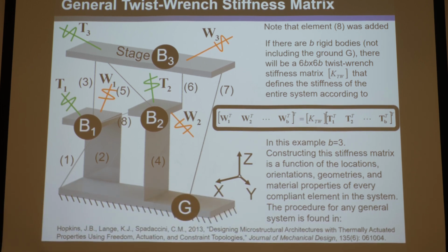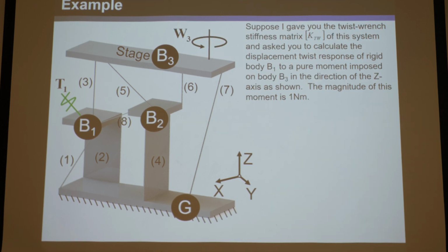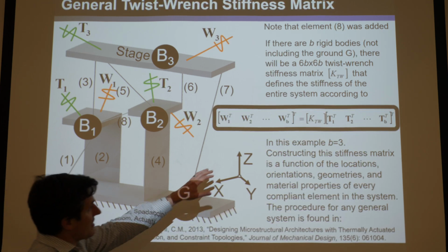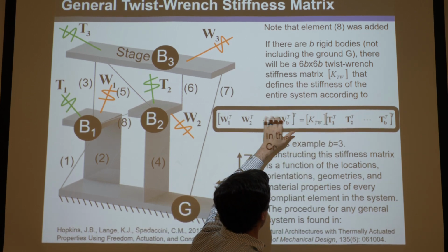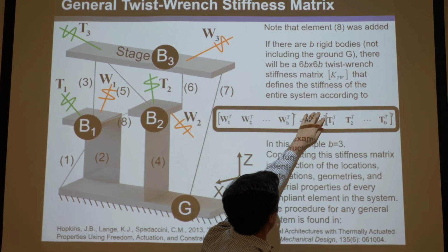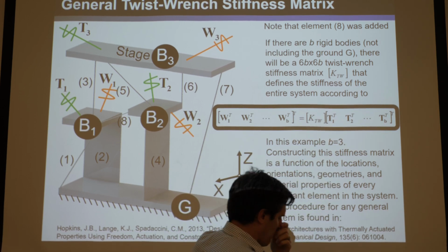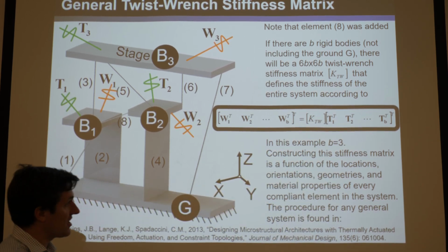And it will do this, okay? So how would you use such a stiffness matrix? Well, just like this, right? If I give you a displacement load, you multiply it and you get this. If I give you the load, and you just invert it, now you find out how they move displacement-wise as a consequence of those loads.